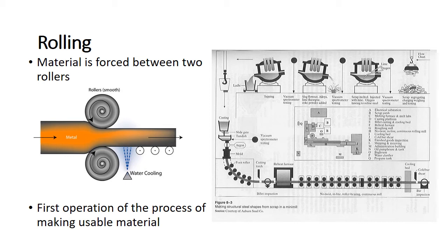There are three stages of it shown at the top. The electric arc furnace is a big crucible with giant graphite electrodes, and those graphite electrodes are electrified. It's basically a giant welding process. You start heating all this stuff up, and as the electrodes lower in, they cause the metal to melt, from the same process that stick welding does.